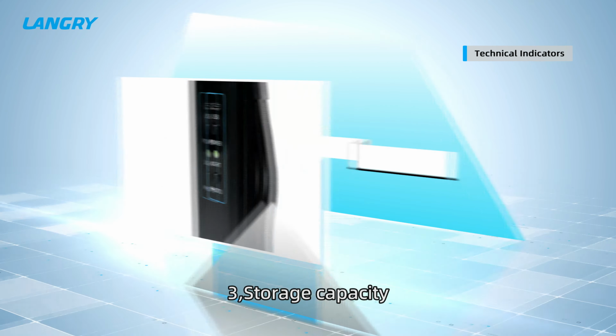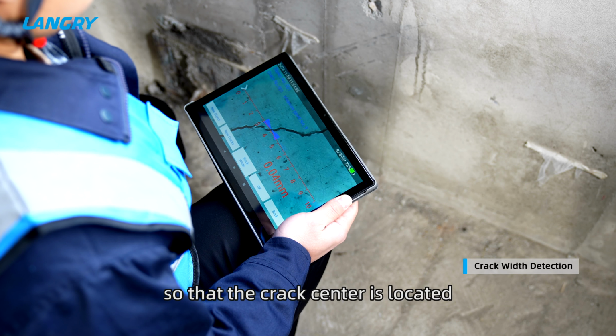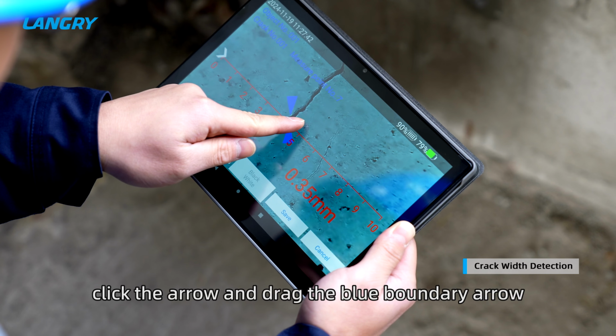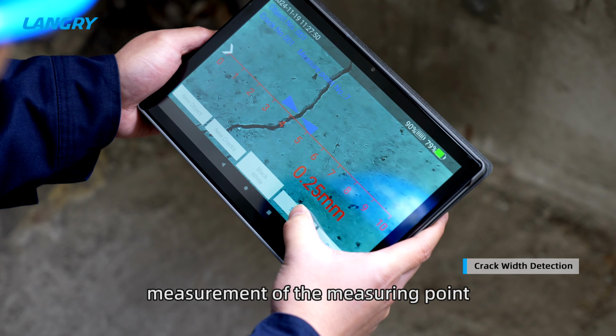4. Crack width detection. First, the probe is placed vertically on the surface of the component to be measured, so that the center line of the probe is pressed near the center of the measured crack, so that the crack center is located in the middle of the screen. After the picture is stable, click the photo button on the probe to lock the picture. At this time, if you need to manually determine the crack boundary, click the arrow, and drag the blue boundary arrow to select the boundary you want to measure. Then click Save to complete the crack width measurement of the measuring point.